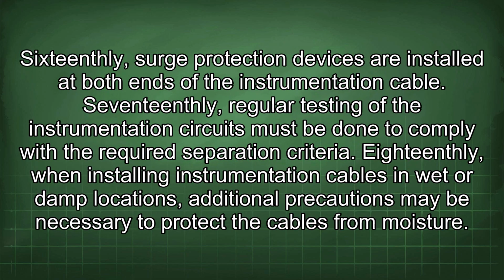16thly, surge protection devices are installed at both ends of the instrumentation cable. 17thly, regular testing of the instrumentation circuit must be done to comply with the required separation criteria.